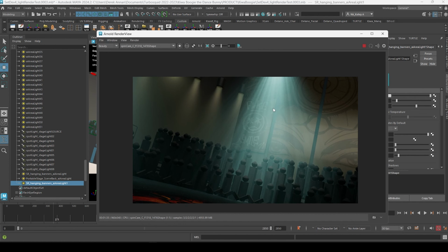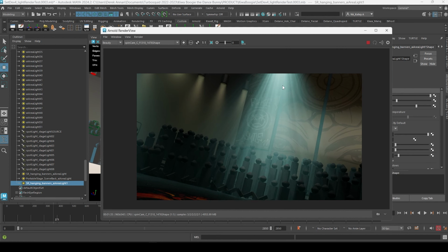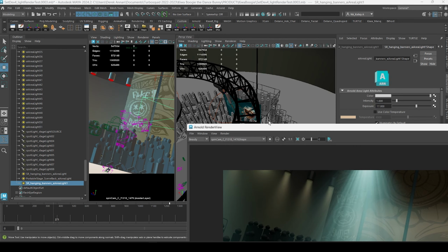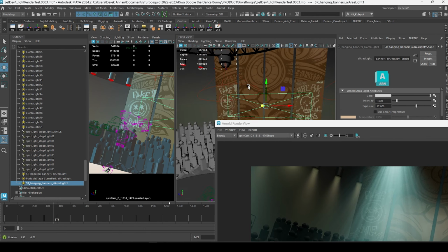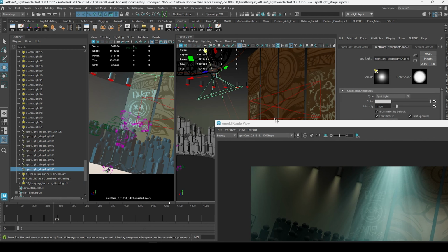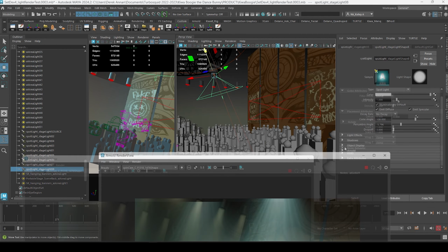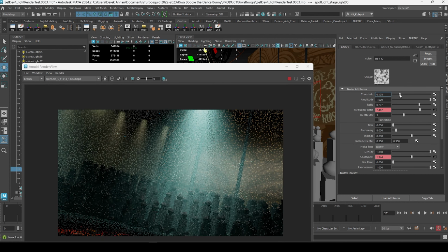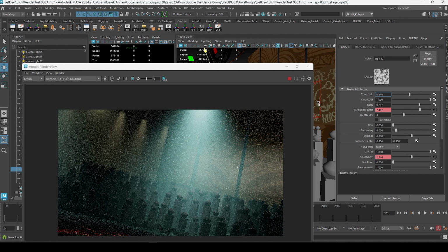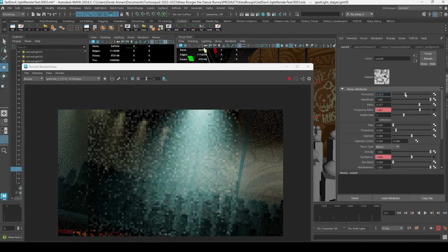But one thing I do want to do is I acknowledge that this light here is a light that really should be in the background. And right now it's pretty high contrast. One of the things I want to do with it is reduce the contrast of the noise that's controlling it. I'm going to pick that light that is the one that's here. I'm going to play with it to decide what that contrast value is going to be. So I'm going to go into its noise and I'm going to crank up the threshold, because cranking up the threshold should minimize the streaks.